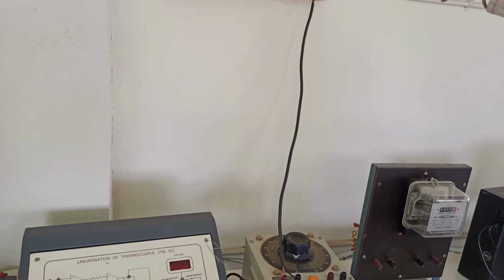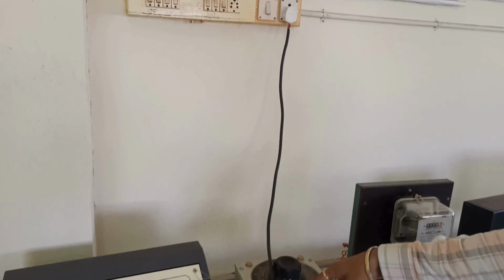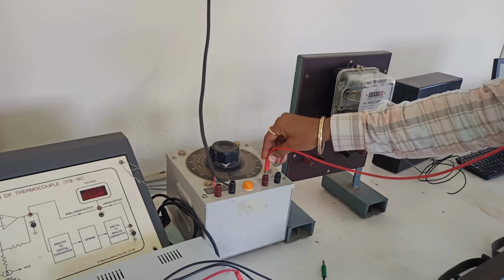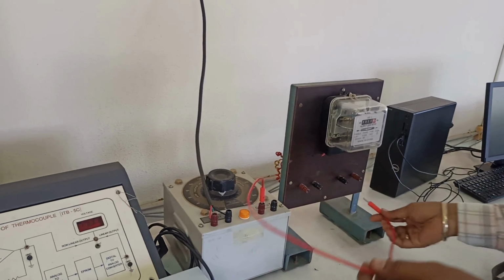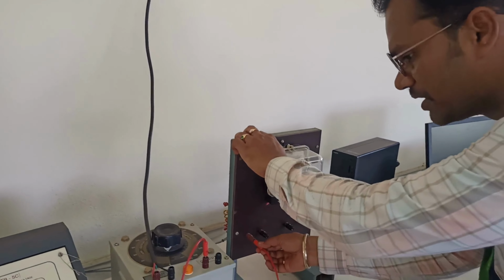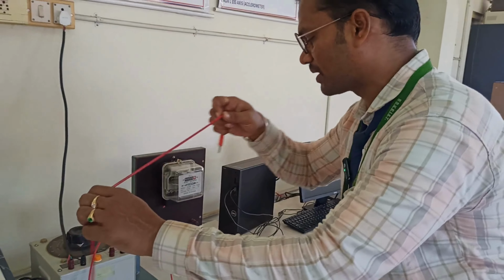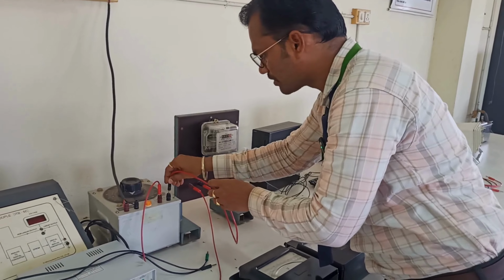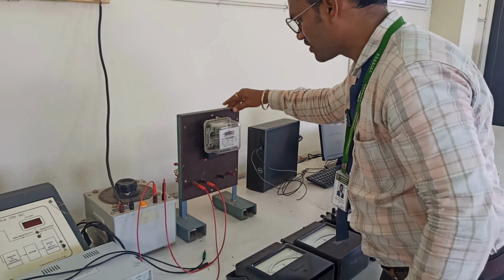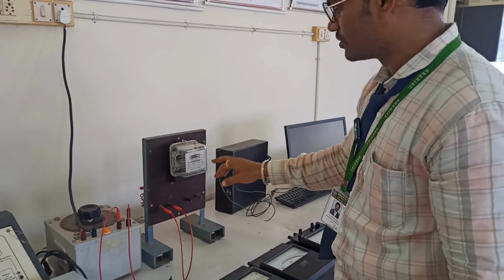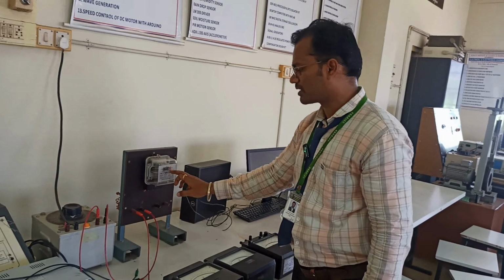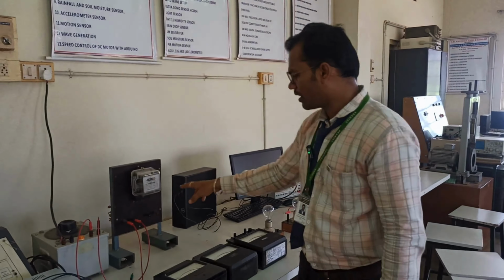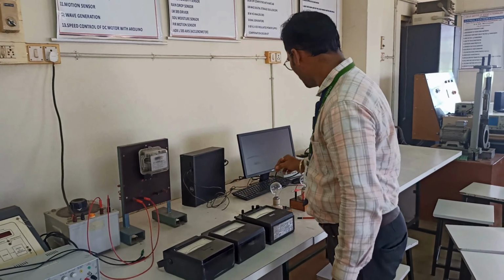You can see here from the supply it is connected to the input of the auto transformer. Now from the output of the auto transformer, we are going to connect to the energy meter input. Okay, positive is nothing but the phase, and from the neutral of the supply we are going to connect to the energy meter. So this is our energy meter, old disk type. This is going to measure the kilowatt hour, which is nothing but how many units are consumed. Okay, now after connecting the input, let's try to give the output connection.